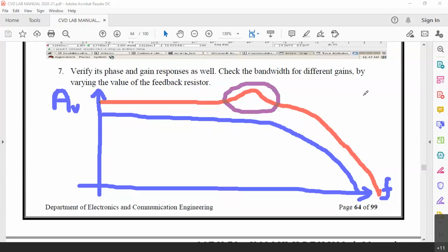So at some high frequencies, somewhere the gain provided by the op-amp may have a sudden undershoot or overshoot. That is because of the impedance there. Now we'll have to model all these 6 plus 2, 8 transistors together, and the impedance will not be ideal, or impedance cannot be so easily calculated that way for each frequency. Now the simulator tool has got the MOS model, and at this particular frequency range, suddenly there is an increase in gain. This is one case I am showing you.